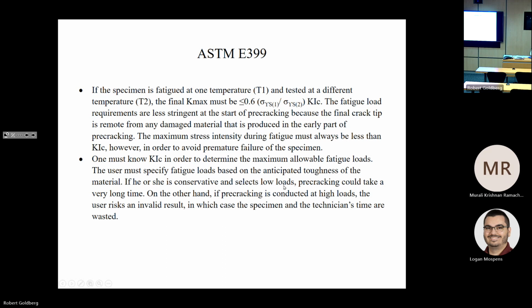Another note is that if you fatigue the specimen at one temperature and test it at a different temperature, your final maximum stress intensity factor has to be less than or equal to 0.6 times the ratio of the yield stresses, because the response of metals is temperature dependent. Just because it's easier to set up all your equipment, you may fatigue it at a relatively low temperature, but then you may do your actual fracture toughness test at a high temperature.